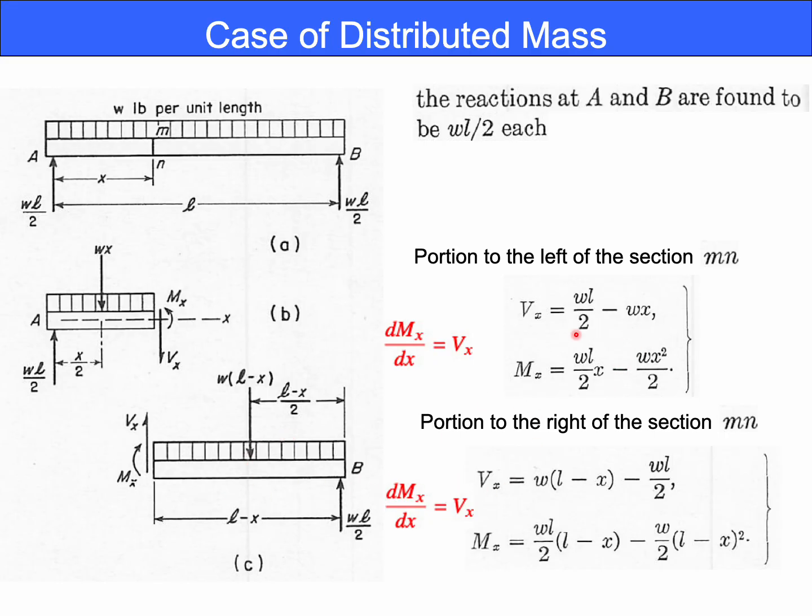And you may notice that if you differentiate this with respect to x, okay, if you differentiate the moment, you obtain the shear force. Also in this case, if you differentiate this, you obtain this. It's very interesting. Therefore, the moment can be obtained by integrating the shear force.